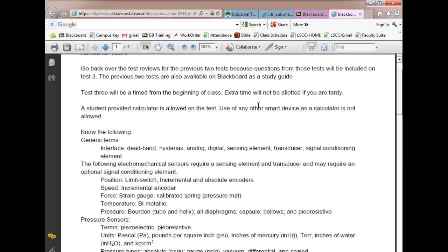So what happens, it also protects the sensor. So if you have a little relay that costs $25 and a sensor that costs $90, your little relay could burn up and still save that $100 sensor, right? Well, these solid state sensors are not cheap. So we protect them. It protects us a bit against short circuits and everything.